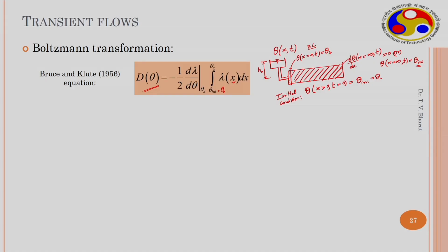Now, such an experiment can be conducted where you have a long column, so that this boundary condition is satisfied and always a constant head is maintained. Then theta also becomes equal to theta s. Then after a certain time, we can measure the water content at different points within the soil sample, either by placing sensors at different locations or by a destructive technique.